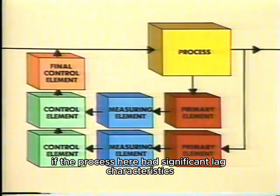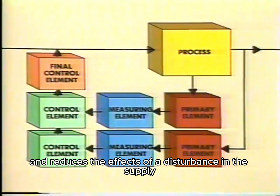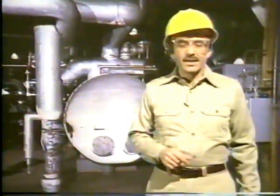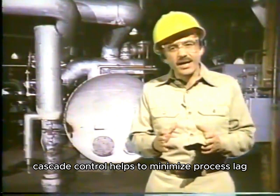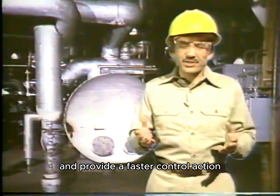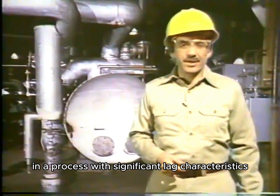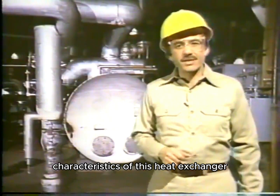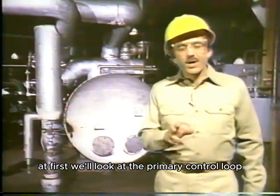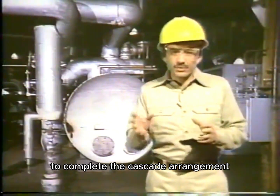If the process here had significant lag characteristics, the secondary control loop divides the lag and reduces the effects of a disturbance in the supply. So theoretically, cascade control helps to minimize process lag and provide a faster control action than would otherwise be possible in a process with significant lag characteristics. Now, let's see how cascade minimizes the lag characteristics of this heat exchanger. First, we'll look at the primary control loop, and then we'll add the secondary control loop to complete the cascade arrangement.